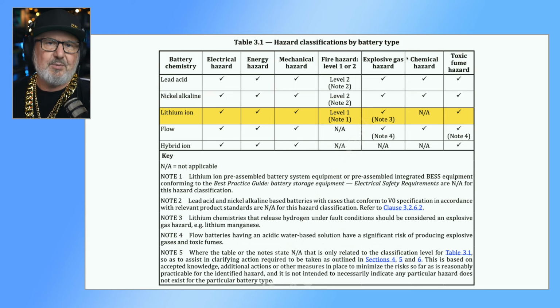And that's also poorly complied with. I often see the toxic fume sign, but it doesn't say what to do, like put on a breathing apparatus with forced air, which is probably what you would need. Because if a lithium-ion battery is venting, the electrolyte as a gas, so that's lithium hexafluorophosphate, gets hot enough to rupture the case and start venting what looks like a white, cloudy fog. That's actually quite toxic, and it's forming hydrogen fluoride in the air and burning your lungs if you breathe it in. Because it's a gas, you can't just filter it out with a filter.